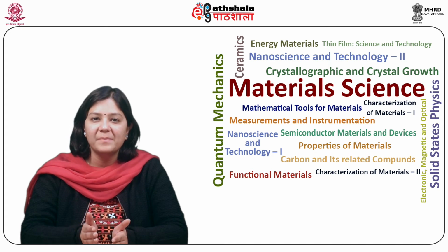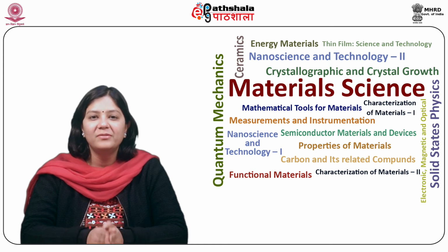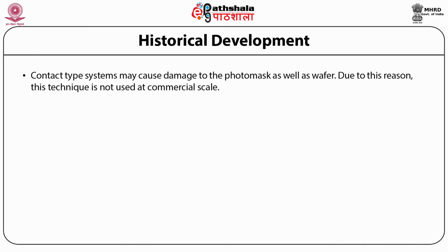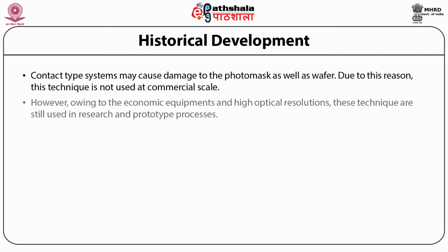With increasing dimensions of the wafer in today's technology, the use of these techniques has become difficult. Contact type systems may cause damage to the photomask as well as the wafer. Due to this reason, this technique is not used at commercial scale. However, owing to the economic equipment and high optical resolutions, these techniques are still used in research and prototype processes.